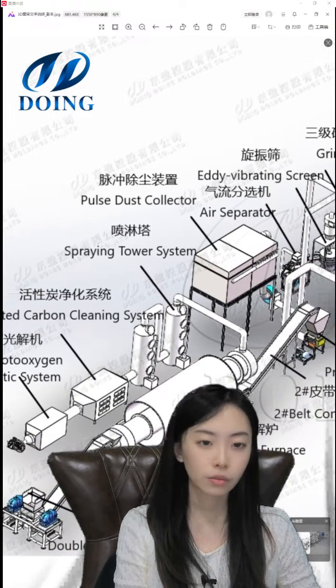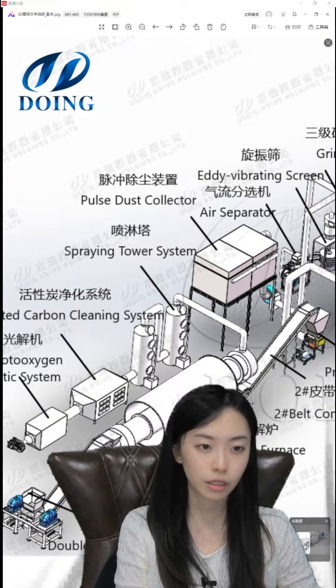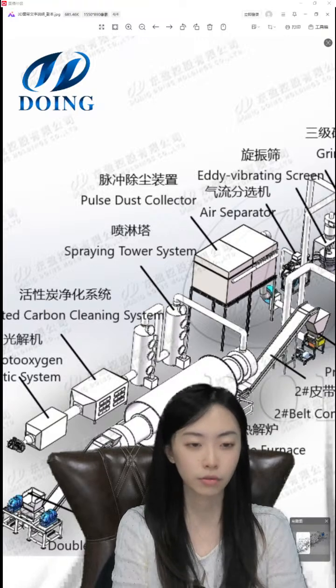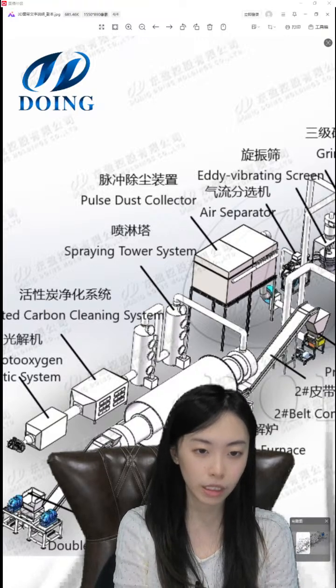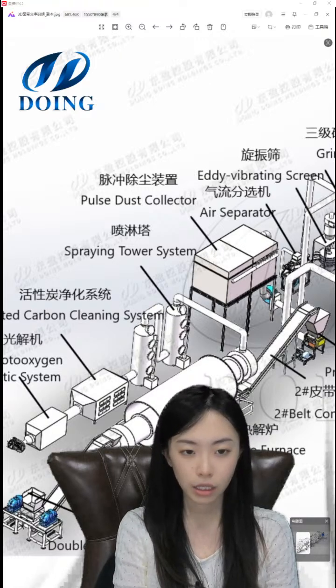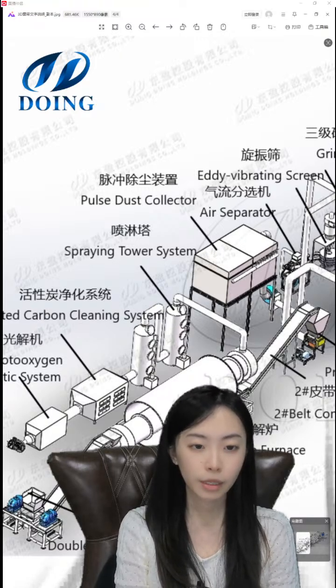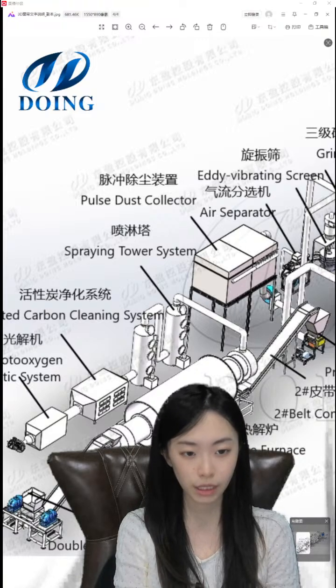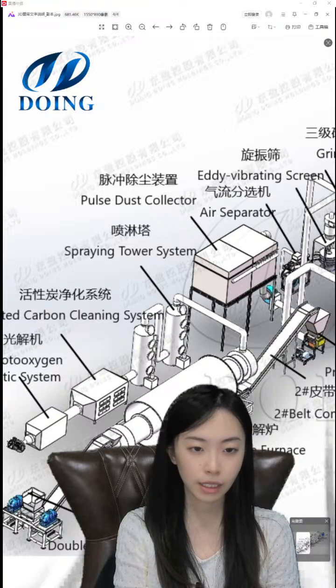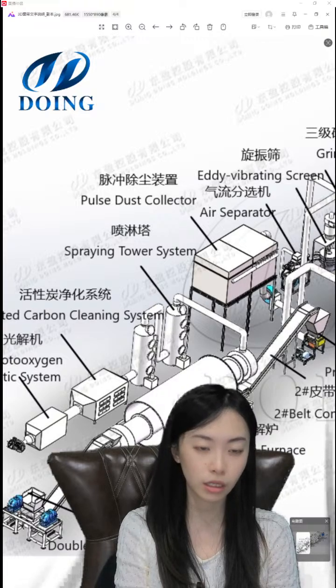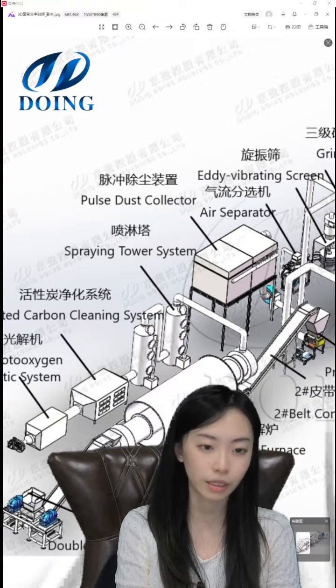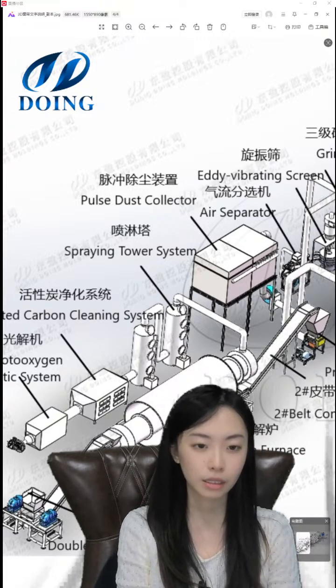And then we can use this carbonization system, this carbide furnace, to heat the raw material and evaporate the electrolyte in the lithium battery. The carbonization furnace uses electricity heating or gas heating. The heating temperature in the furnace is 100 to 450 degrees. The electrolyte in the battery is completely evaporated to facilitate subsequent harmless treatment. This is this step.